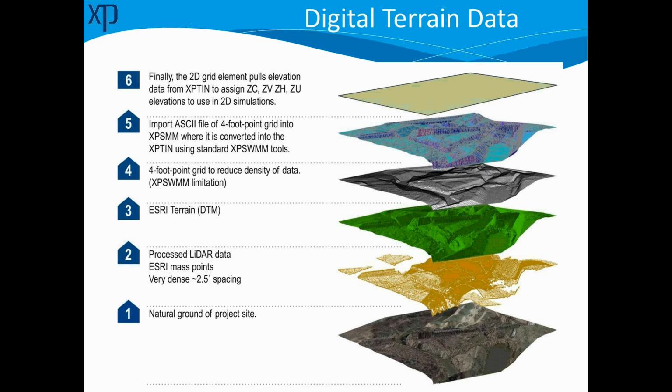case, a grid cell, that's all it sees is that cell. Right now, currently on the market, what they're looking at is that cell, and the depth is averaged for that cell. And all the software, to my knowledge, is the same, and looks at that as a cell for calculation purposes. So let's not romanticize or over-imagine what our two-dimensional model sees. It sees this terrain as a cell. So more is not necessarily better, but certainly we want our good terrain, and we want it to pick up all the undulations that we want our model to see.